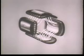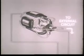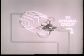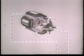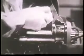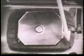These pole pieces have conductors wound around them. When current flows through, it builds up the magnetic field and the attraction of the poles is sharply increased. This strengthens the turning power of the armature enormously. Here is the pole piece and field winding, as seen in an actual starting motor.